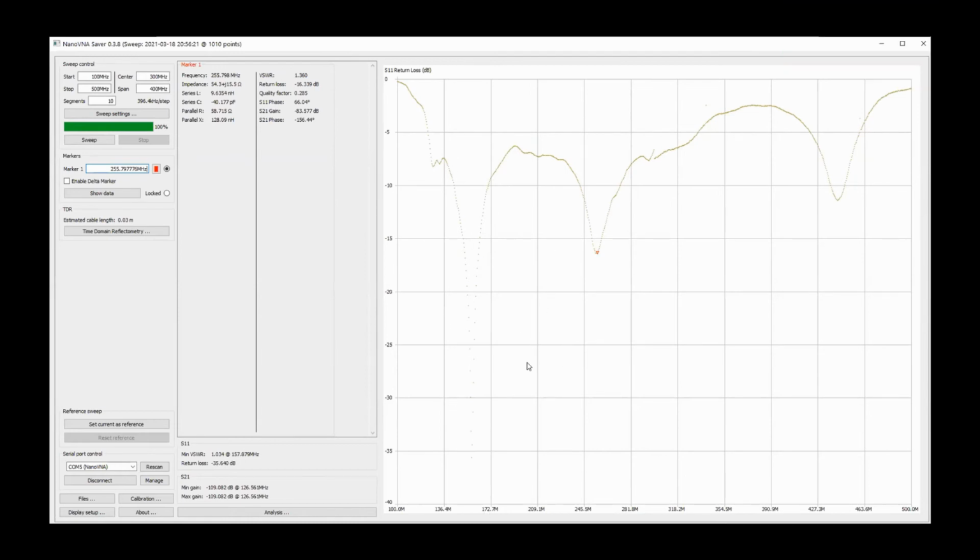So, Greg, it looks like it's updating as it goes across the horizontal scale 3 or 4 times. Is that the software doing the separate tests and then merging them all into one graph? Yeah, exactly. I've set it up for 10 sweeps, so it's going to take 10 sweeps, 101 points in each sweep, and then it merges it all together in one graph. And each point is each point that you see when you can see the individual dots on the screen. Yep. Yeah, that's each frequency point in the sweep.